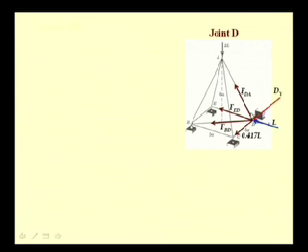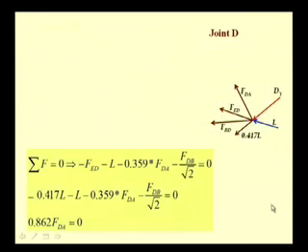The direction cosines of various forces can be obtained from the geometry of the truss, and we have already determined the magnitude of this force in member CD, and so we have 3 unknowns, that is the force in BD, force in the element ED and force in the member DA to be determined, and these can be determined from the force summation equation.